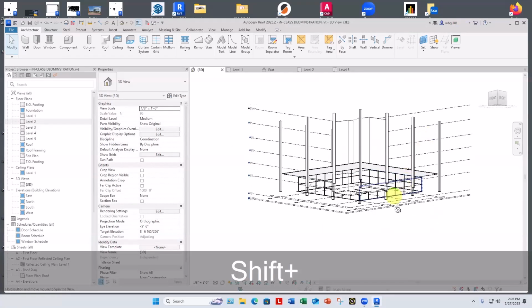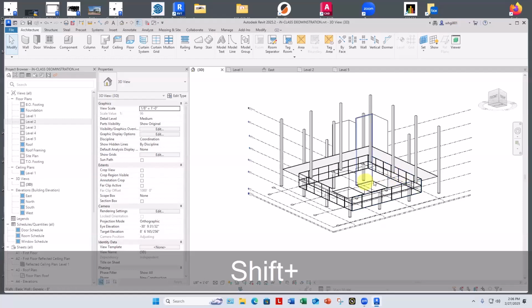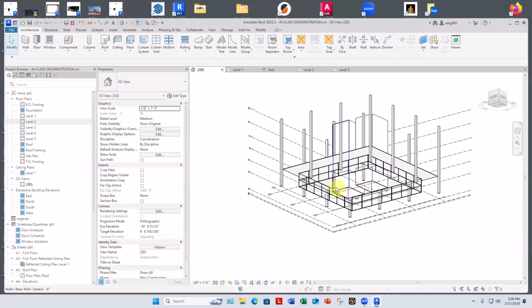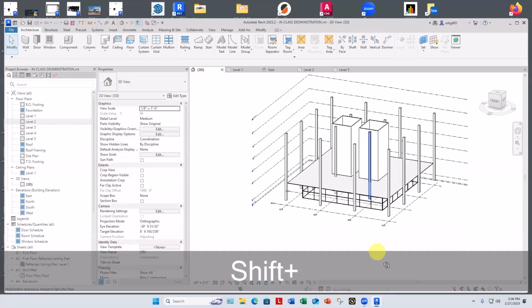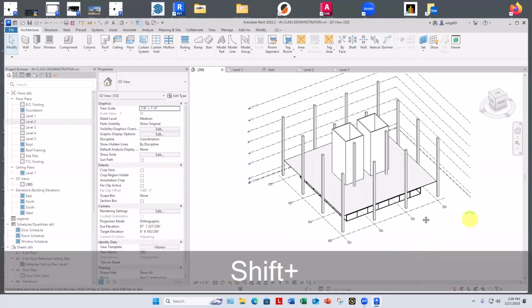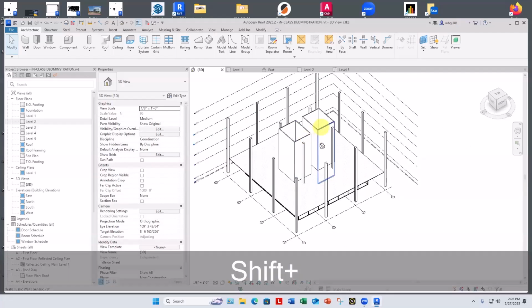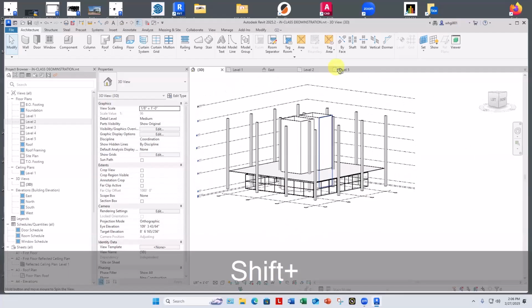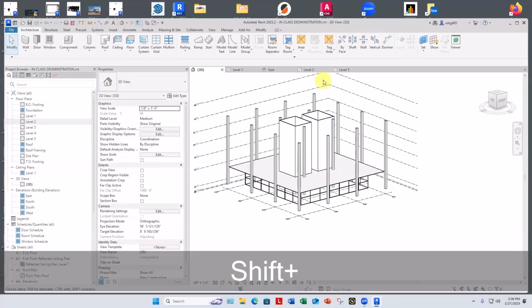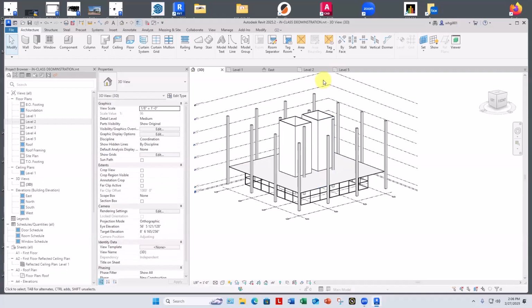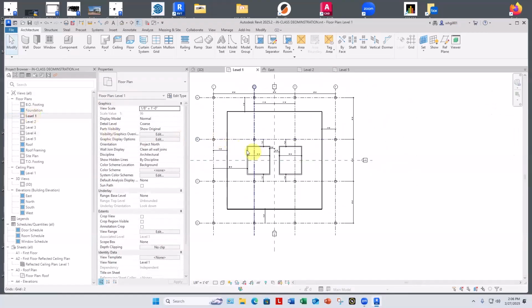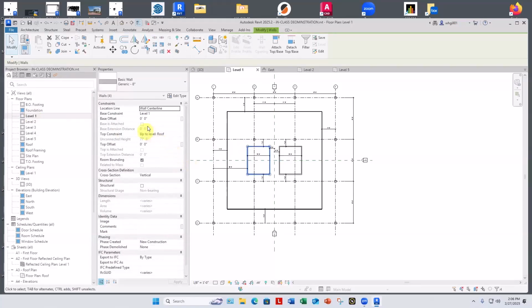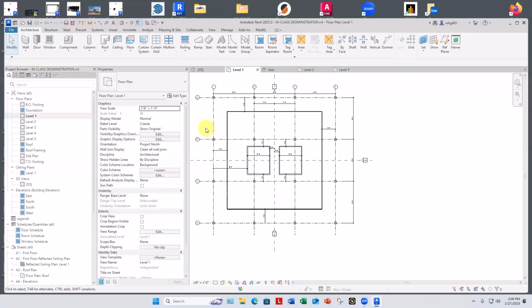If you haven't yet, go back to your first floor plan and extend all these guys up to the roof. These 8 walls, the walls of the shaft, we want to go all the way up to the roof. That's for all that heating and ductwork. And yeah, I would hover, tab, click, and say they start at level 1 and go up to the roof. Yeah, we had done this together.